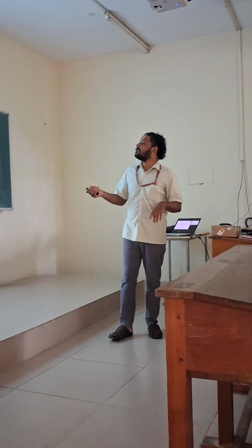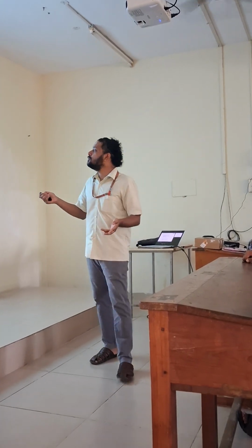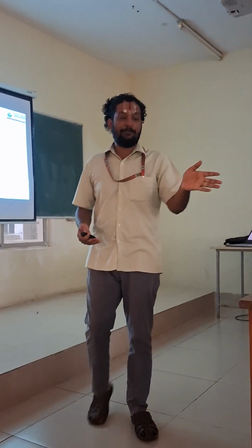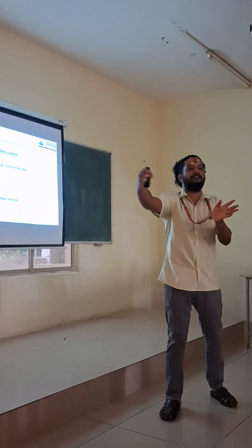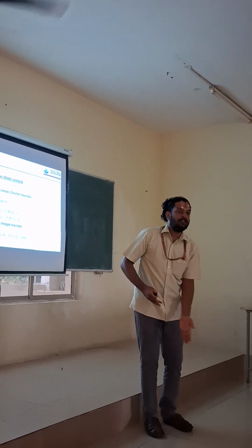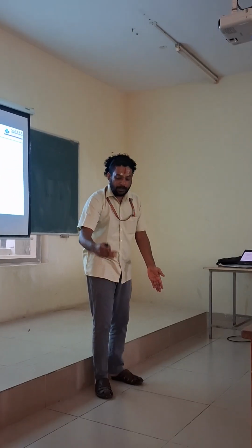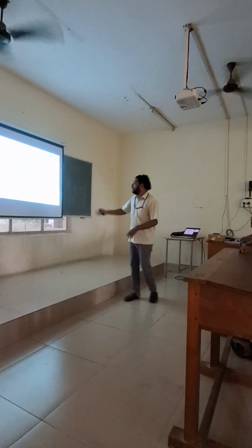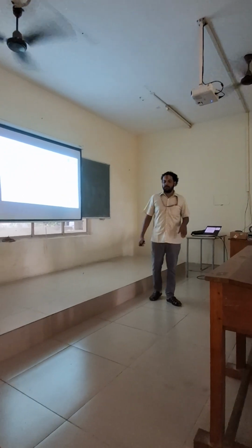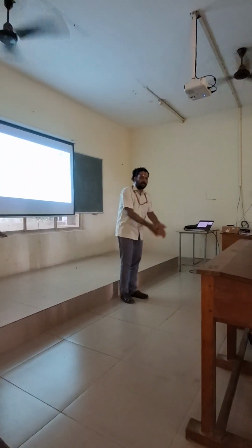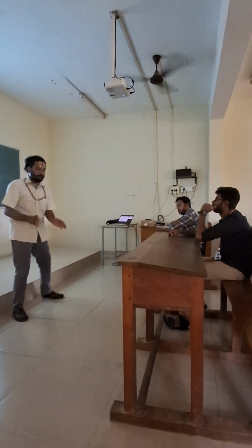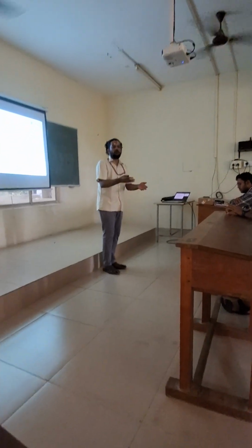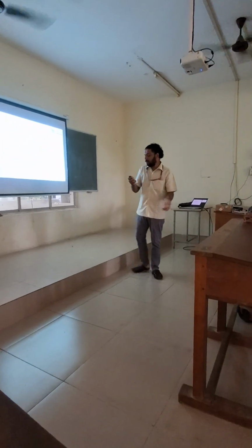For, let's say, a voltage controlled ohmic contact, we apply what is known as a Dirichlet boundary condition, where we apply a certain voltage, and that voltage has to be kept. It's a constant voltage, and that will basically drive the next points. This is where I have the Dirichlet boundary condition. The points over here influence the value here, but this value will influence these values. That's all it means. Then we have what is known as a Neumann boundary condition, where I have points here. This is my boundary, but I also have points here. Values here will have an influence on the values here. That's what a Neumann boundary condition means.